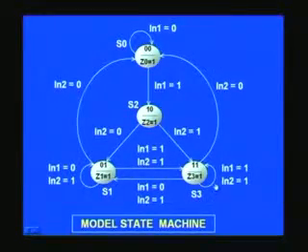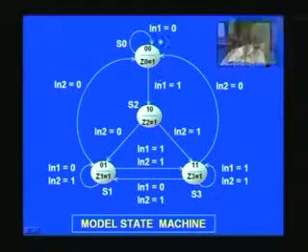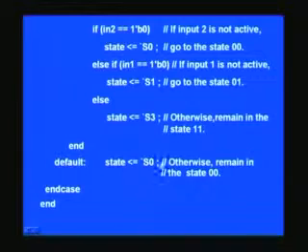So we were in S3 state here, right? When in2 is 0, it returns to, do you remember this? Anyway, what we found is in2 1 and in1 1. It should continue to remain in S3 state, right? If in2 is 0, it returns to S0 state. This you can verify once again. We are here. If in2 is 0, that is the top priority we have given. So it doesn't really care for in1, right? That's what we meant right in the beginning. So if it is 0, straight away take to S0, right?